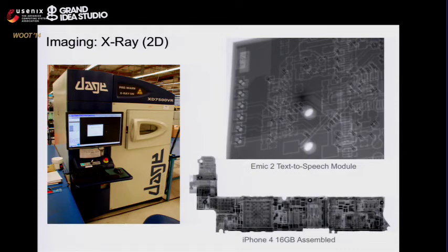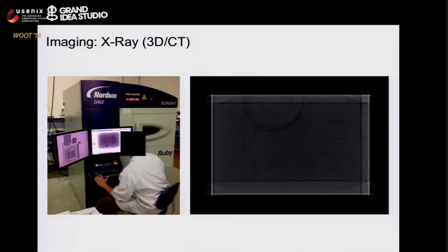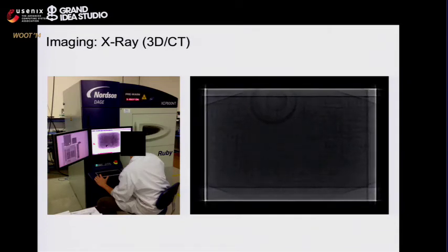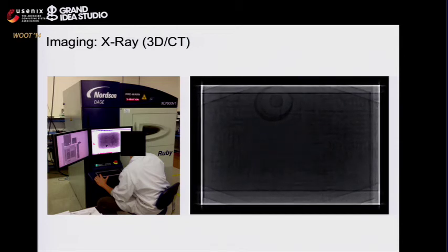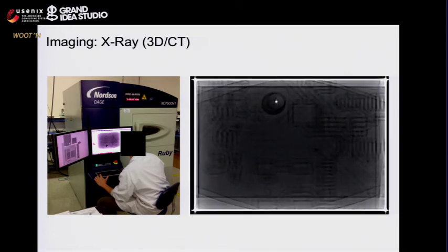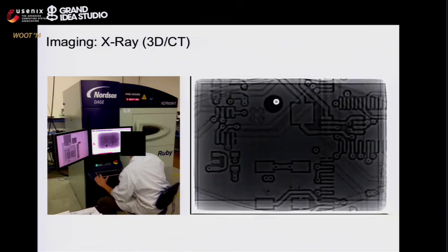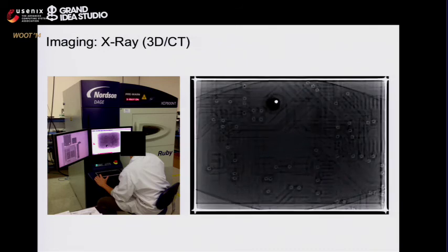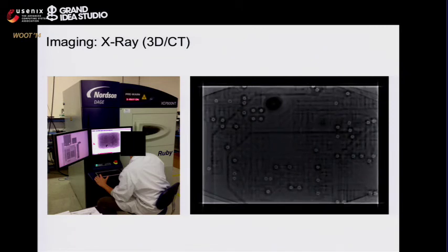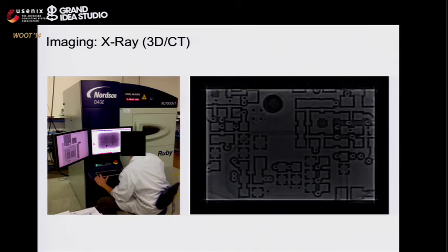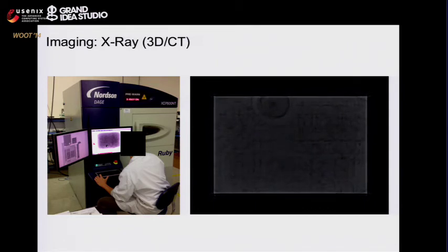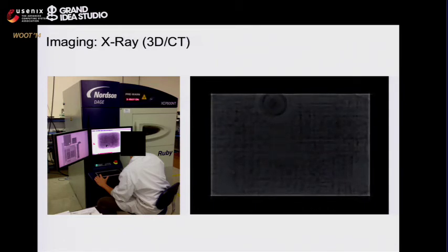But it was still worth doing to let us know that, if that was the only option, then you could go with that. But really, 3D X-ray CAT scan is commonly done for analyzing ball grid array, BGA solder balls underneath parts if there's failures. In this case, we ended up going to a place with a test board of mine. We stuck it in an X-ray machine that had this CAT scan functionality, which basically takes lots and lots of different 2D images at different angles, and then post-processes all of that and gives you slices back.